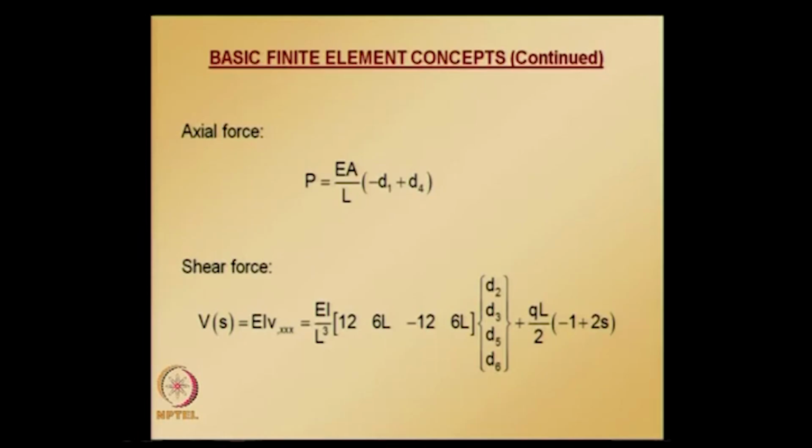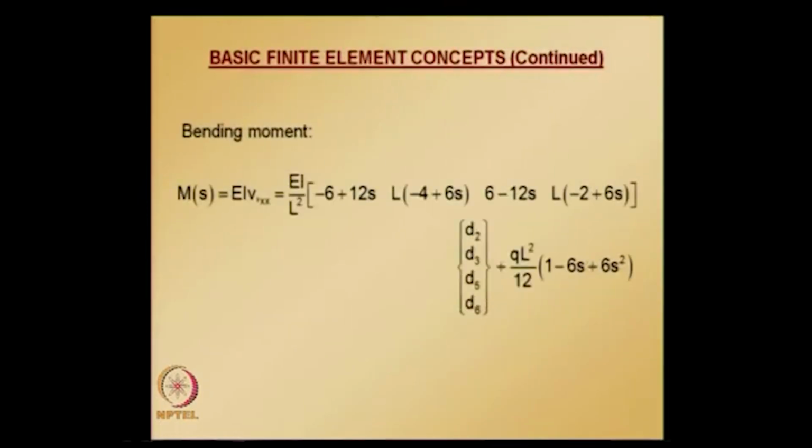And since this frame element is subjected to distributed load, we need to apply fixed end correction, where S is equal to 0 corresponds to node 1 and S is equal to 1 corresponds to node 2. Similarly we can also calculate bending moment, where we also need to apply fixed end solution correction. So this is the procedure for solving frame problems.